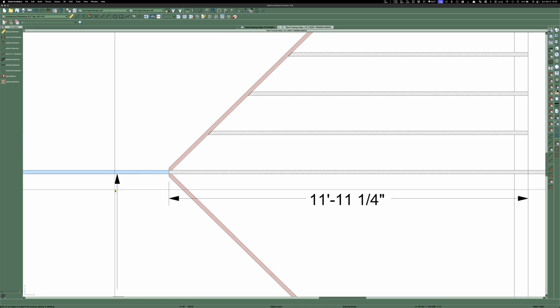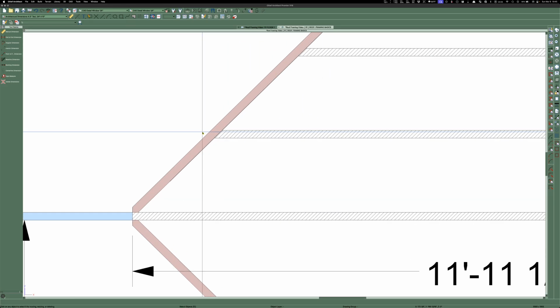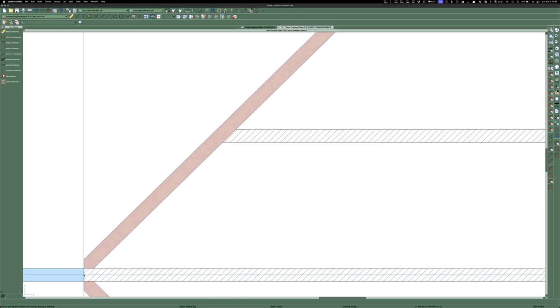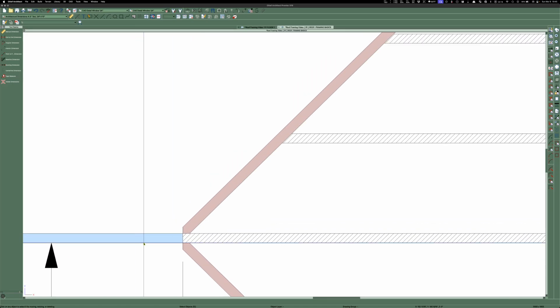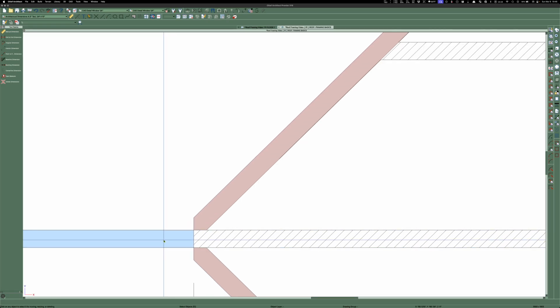If you do the Construction Master and you tell it to do your jacks, they're going to be wrong, okay? The reason they're wrong is they do their calculation off of a center line, and they make the assumption that they don't take the thickness of it. They go from the face, okay? So when you get a run, you're coming from the face of this ridge, and the thickness of that is 3/4.